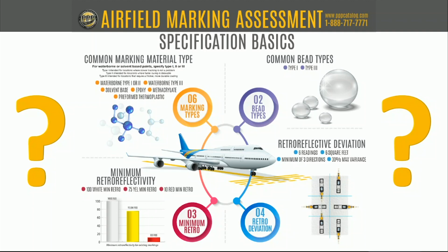Okay, great. And of course, being the provider of that instrument, I'll add to that just a little bit that remember that meter is scanning left to right at about a 1 meter width, and it's actually checking for that lateral deviation as it sweeps across and scoring that marking for that as well. So even though it's longitudinal, in its direction of travel, it's also taking this lateral assessment at the same time. So that's pretty cool about it.